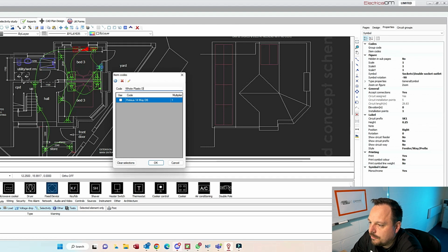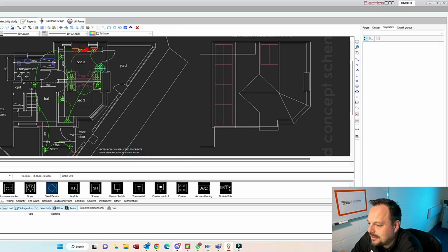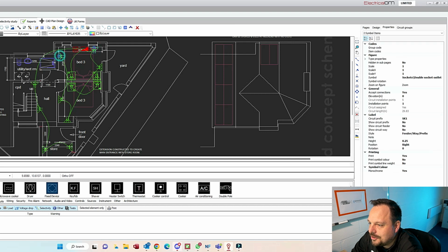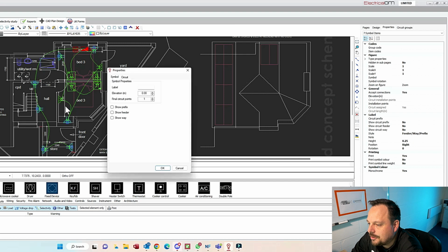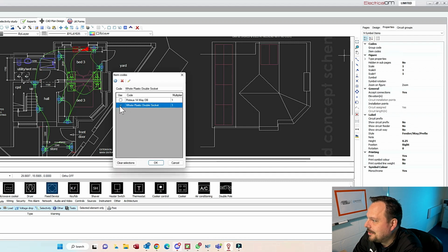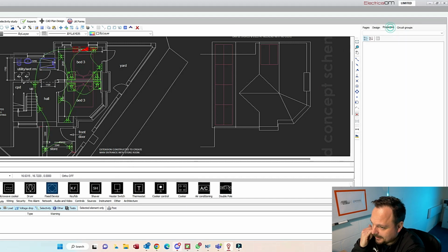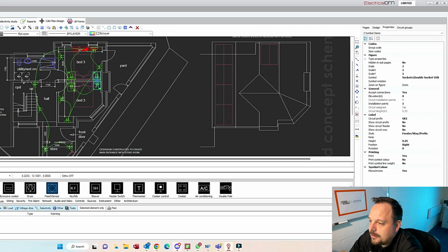So we now need to go and create the socket outlets, and excuse the bad spelling of white there, I've not noticed that while I've been recording the video, but we can select those now, and if we run around and choose all of those sockets on our drawing and then make sure we tick that into the list at the side, we will be able to get a list of materials ready to take off to the wholesalers or check we've got stock in the unit straight on for this job. So we've got our 9 items in that case, and I'm just checking that off camera to make sure it's populating over to the list of materials, and it is.